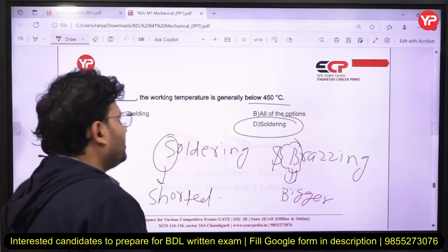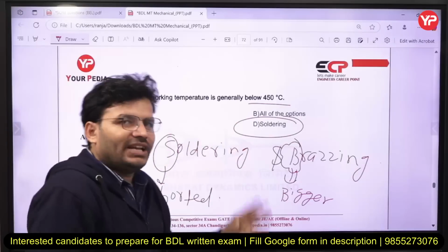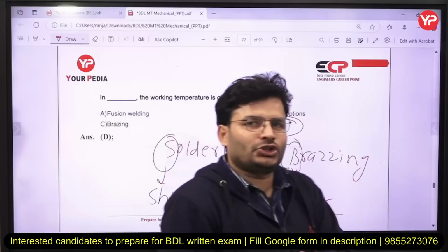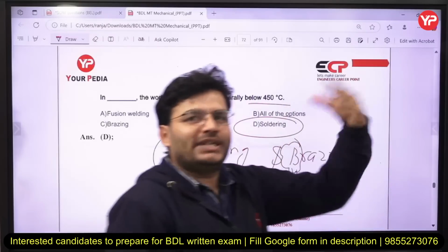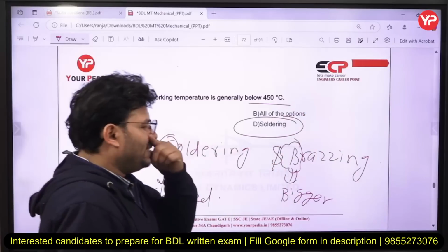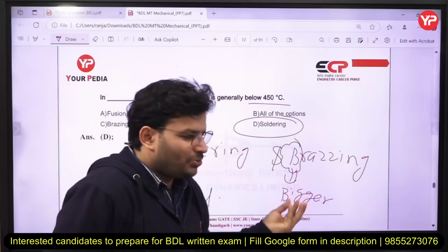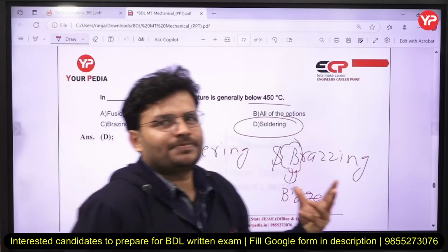If the working temperature is less than 450, it will be called soldering. If more than, meaning bigger than, 450, it will be called brazing. By this keyword, I know most students get confused, even in the exam.